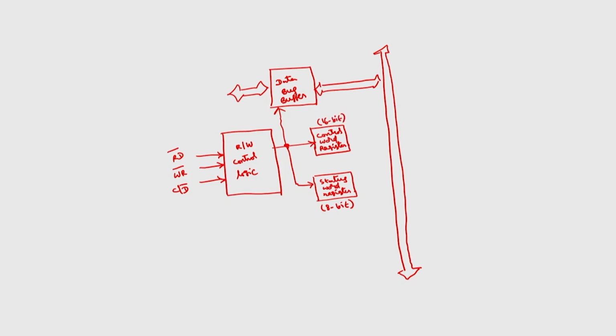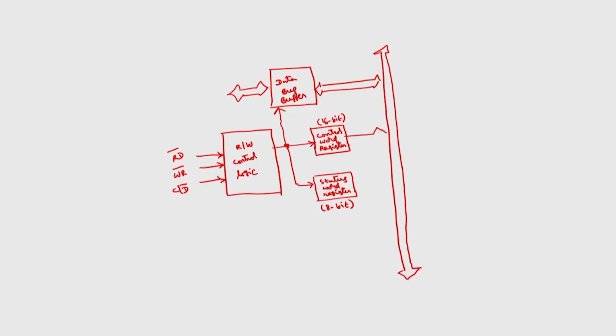So, the microprocessor will write some data into control register. So, the direction will be here from control word register to internal data bus, whereas the microprocessor can read the status of 8251, so the direction will be like this. As the name implies, in case of control word register, write bar is 0 here.